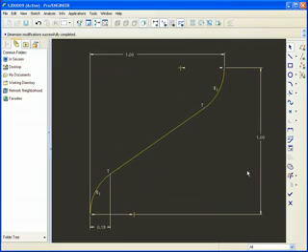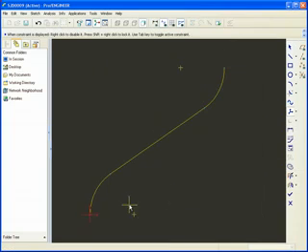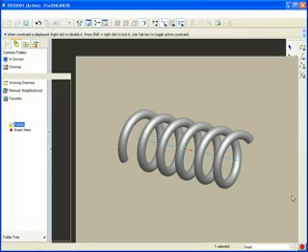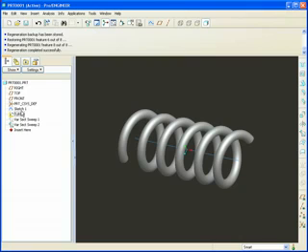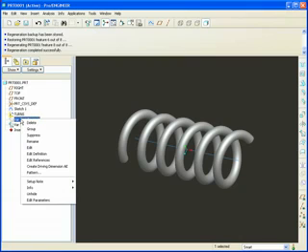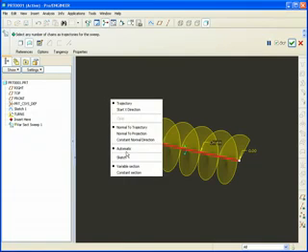Now the last requirement for a graph feature in ProEngineer is to include a coordinate system where you want the 0, 0 to be. So now I've got a graph feature that I can use for my helical sweep. So I'll drag it before it so I can use it in its derivation. I'll unhide that sweep. I'll go back to its definition and its sketch.